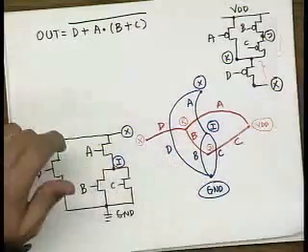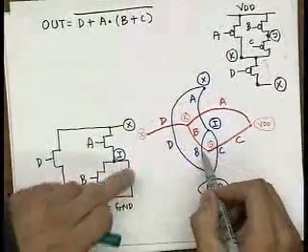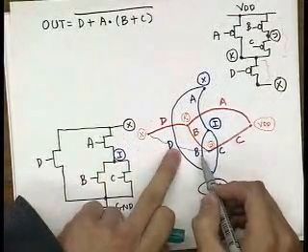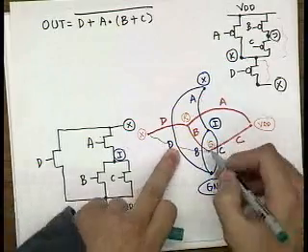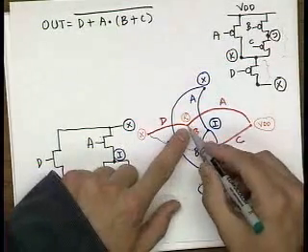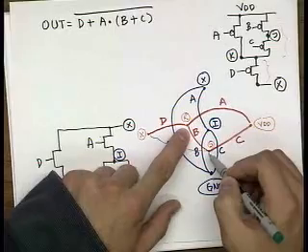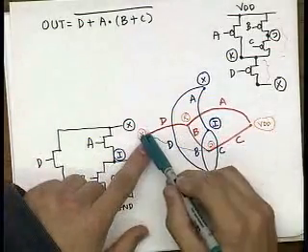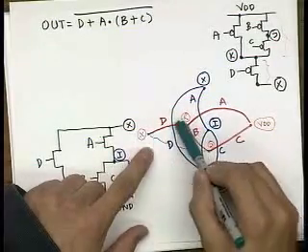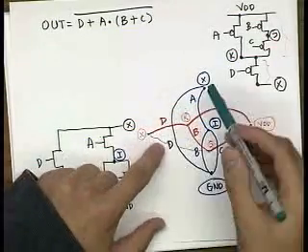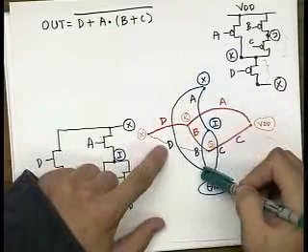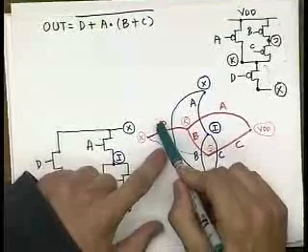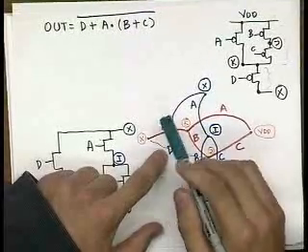For example, this would be an invalid connection. If you want to connect X and J, you can't do this because you are crossing both D and B. In order to connect J, you have to connect over here to K. That's the strategy you follow. Each node connects through a transistor that has the same label as the edge it's crossing over. If this one crosses over D, then this will be my PMOS transistor controlled with the D signal, and so on.